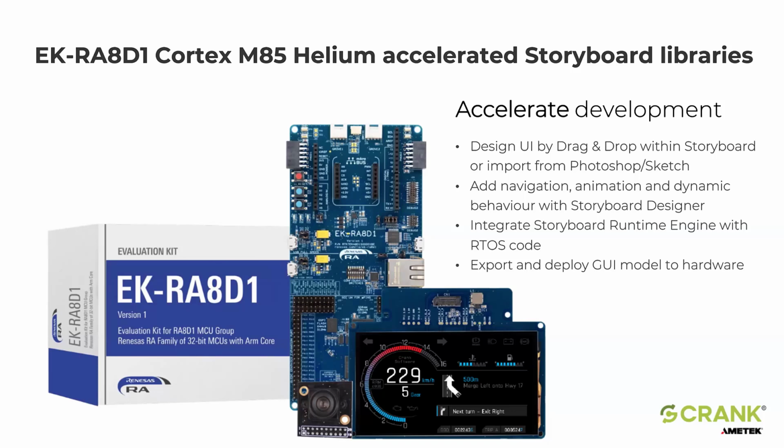With display size, the resolution is the most important factor. Resolution to us is pixels. Pixels means memory, and you can have 2 or 4 bytes per pixel. So in terms of looking at your solution architecture, you're specifying your hardware. You can look and see how many pixels are on your display, and you can calculate the frame buffer sizes. And these are often some of the largest factors. So I'll go into more detail.